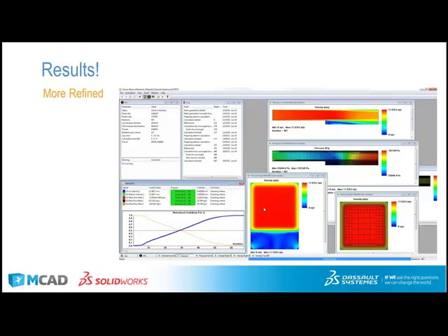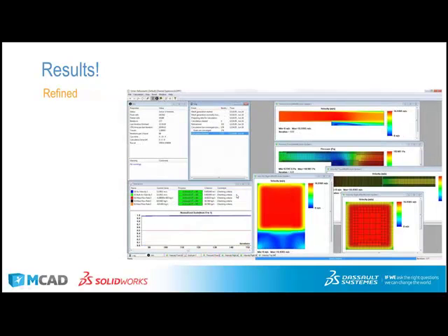You'll also notice when I go into the results that these refined meshes take a significantly longer time to solve. It should be noted that if I look at refined, we have a solver time of 15 minutes and 4 seconds, and that was with a decent amount more mesh added at 132 iterations, and then it went another 40 iterations to smooth out the cells. So not bad. It was the same as the CPU time alone, but I got much more high fidelity results. But I could have had the entire thing in 3 minutes and still had my numbers.